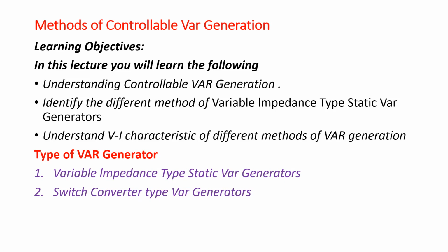transmission line. The advantage of midpoint shunt compensation is that the power handling capacity would increase up to double that of without shunt compensation. The second point we discussed is that for the radial line, the best location of the shunt compensation is at the end or near the load condition. These are the two points which we have considered.